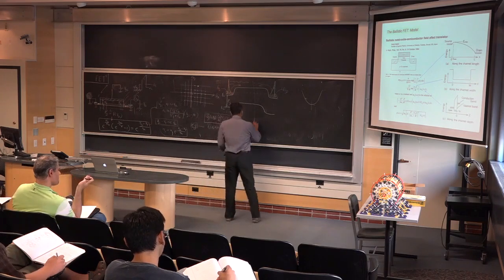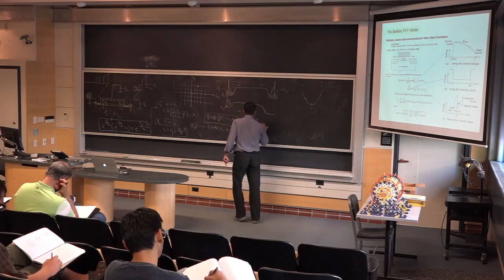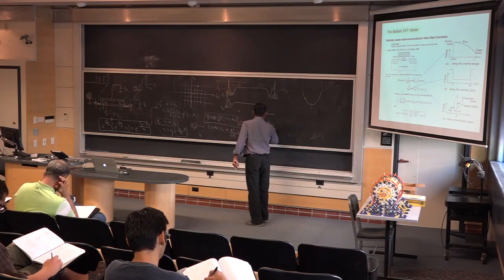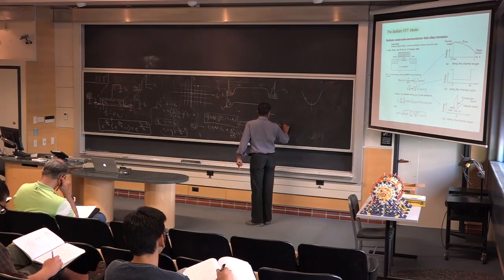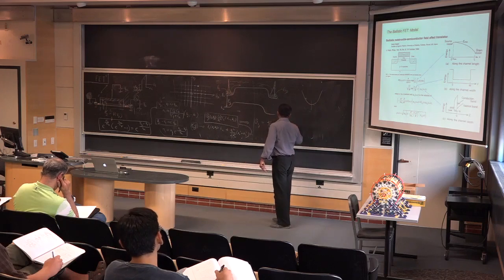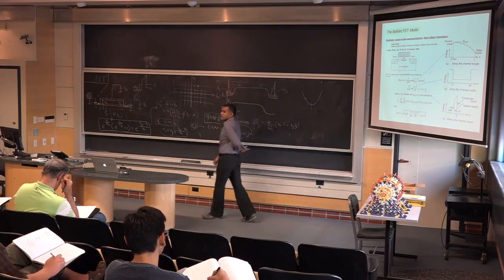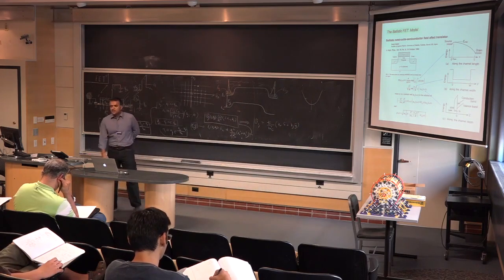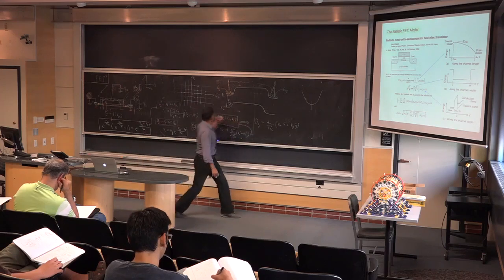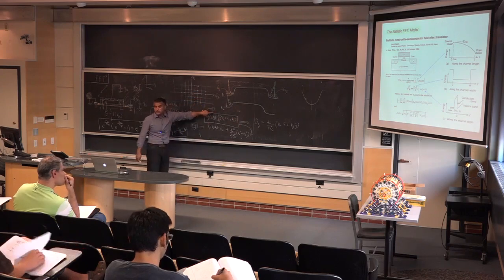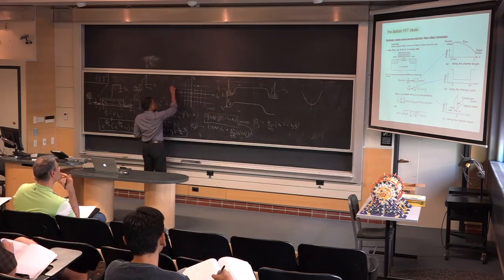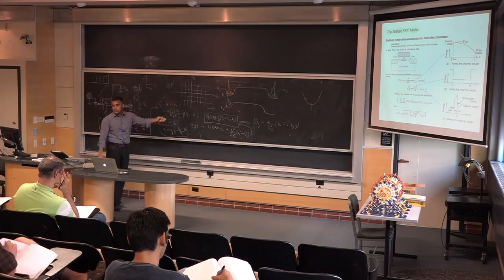When you take the gradient, what you get is the group velocity, h bar over m star of the conduction band times kx, and this will be oriented in the x direction in k space, plus ky times y hat. That's how you take the gradients. When I write x hat, it's just that direction. This is the direction we are labeling as x hat. You can label it whatever you want. It's just a direction in that space, and that's y hat. Makes sense? That's the group velocity.